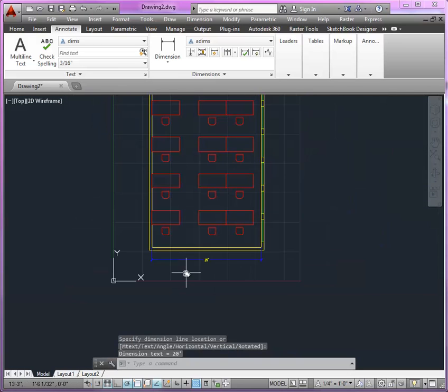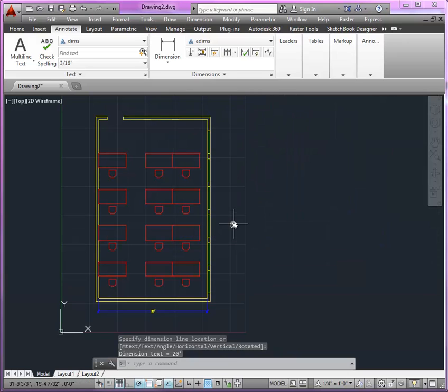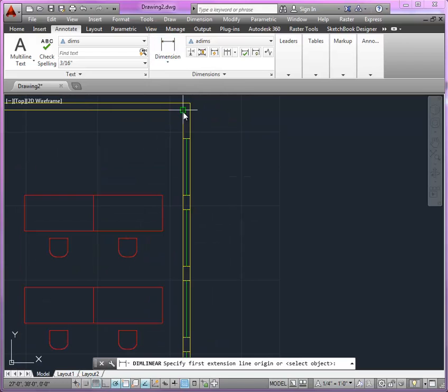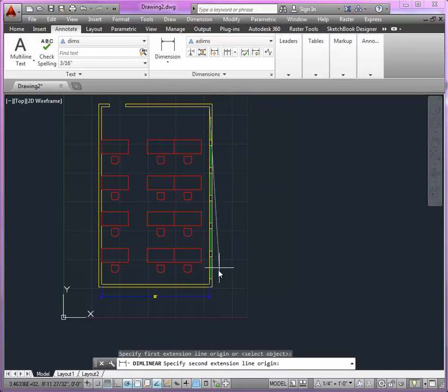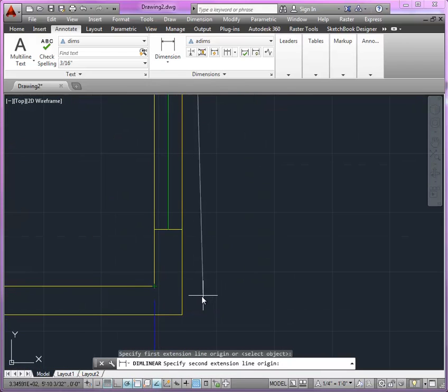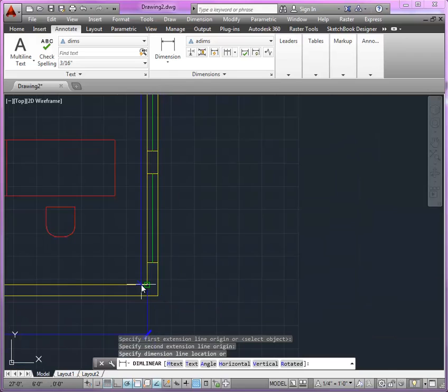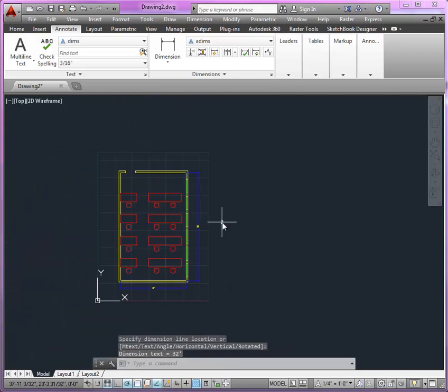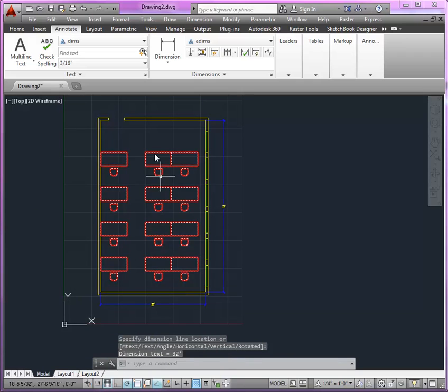Keep it away from the object. And notice how I'm using the zoom command. So once again, linear dimension to do vertical and horizontal. Notice that's the first click, and see how I zoom in, get in close. You don't want to snap to the incorrect point, right? Get in close and then zoom out to do your third point. Okay? And that's how you want to do that.